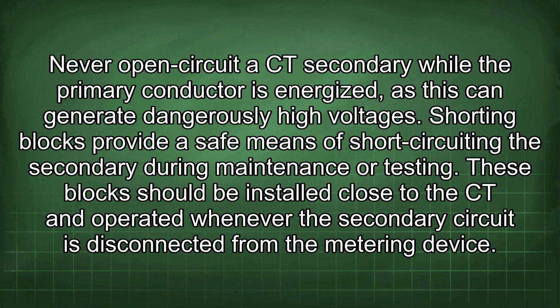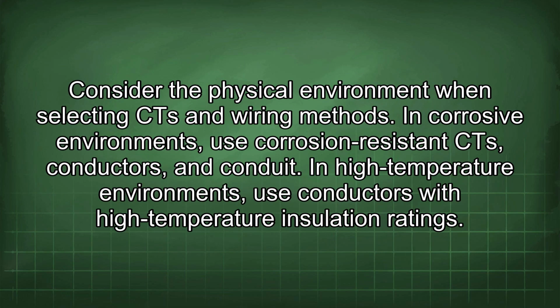These blocks should be installed close to the CT and operated whenever the secondary circuit is disconnected from the metering device. Consider the physical environment when selecting CT and wiring methods.